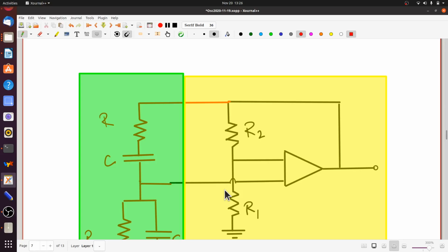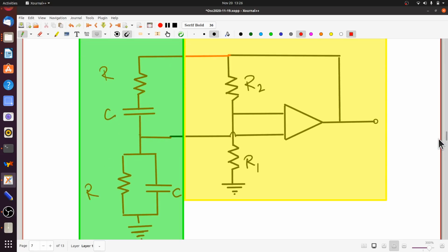Now, when this circuit was first designed, this, by the way, is called the Wien Bridge oscillator, basically because if you look at this part of the circuit, the resistors R2, R1 and the lead lag network together, and just redraw it a bit, you should be able to convince yourselves that what you have is the Wien Bridge, which we discussed when we talked about AC bridges, again very early on in our course. That's why this is called the Wien Bridge oscillator. However, Wien had nothing to do with this particular oscillator. This was designed a lot later.